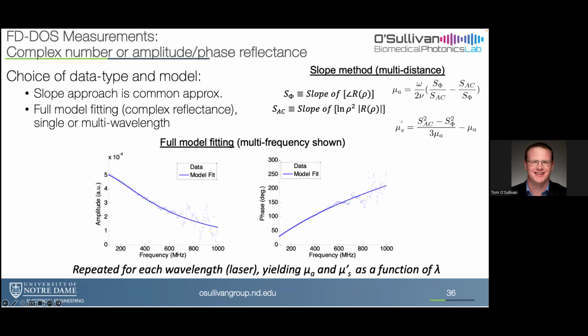There's a phase delay in the electronics, and in the delay that goes through your fibers to your tissue. So you have to calibrate that all out. And that calibration is susceptible to those same signal to noise ratio issues. So basically what's happened is we're getting a really poor calibration, and what we're seeing is some of the effects, or the ringing, that the system is contributing.